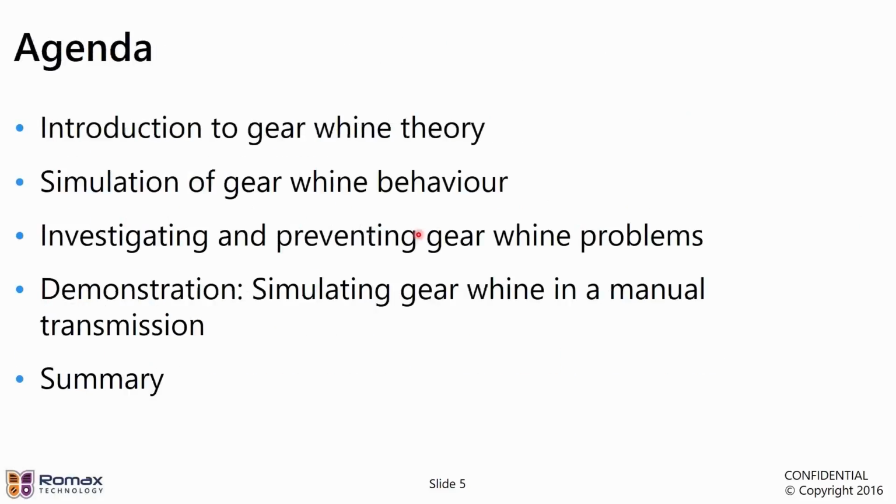So today we're doing the introduction, and here's what we're going to be talking about. We'll have a brief introduction, and I mean brief because it is a very big topic, but just to give you a flavour of what gear whine theory is, what the causes and effects of gear whine are. We're going to look at how we can simulate gear whine behaviour, and we're going to look at some hints and tips, if you like, on how to prevent gear whine problems, both in terms of things you need to consider and things you need to simulate. And then we'll finish off with a demonstration of simulating gear whine using Romax Designer.